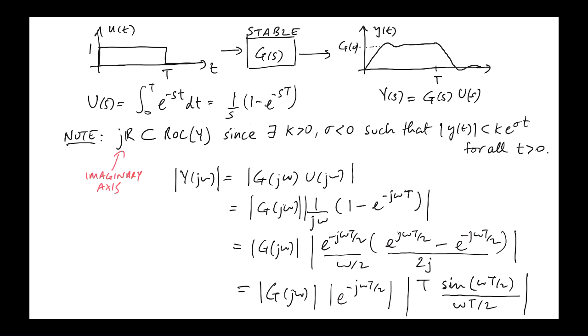All right. So let's see what the transfer function evaluated at s equal to j omega can tell us about the behaviour here. You can see that what we're getting out of this stable transfer function is a distorted version of what went in. Okay, in steady state, it's exactly the same as what goes in, but when there are changes, okay, what comes out is a distorted version of the changes that go in. Okay, and the frequency response, so the transfer function evaluated at s equals j omega, tells you something about the distortion.